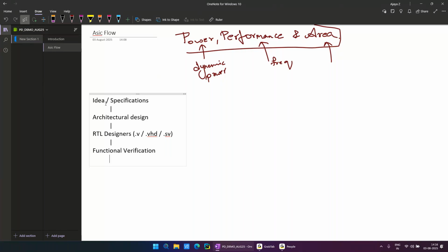In simple terms, after each and every stage you have to remember that we need some kind of verification. So the next step is functional verification. They will use test bench codes, or different ways, to verify that functionality. Now, as I'm going to have multiple instantiations, let's say 3 million gates, 10 million gates, writing all that test bench is very difficult. So that also is kind of automated. They will use some other coding languages to do that algorithmic check.